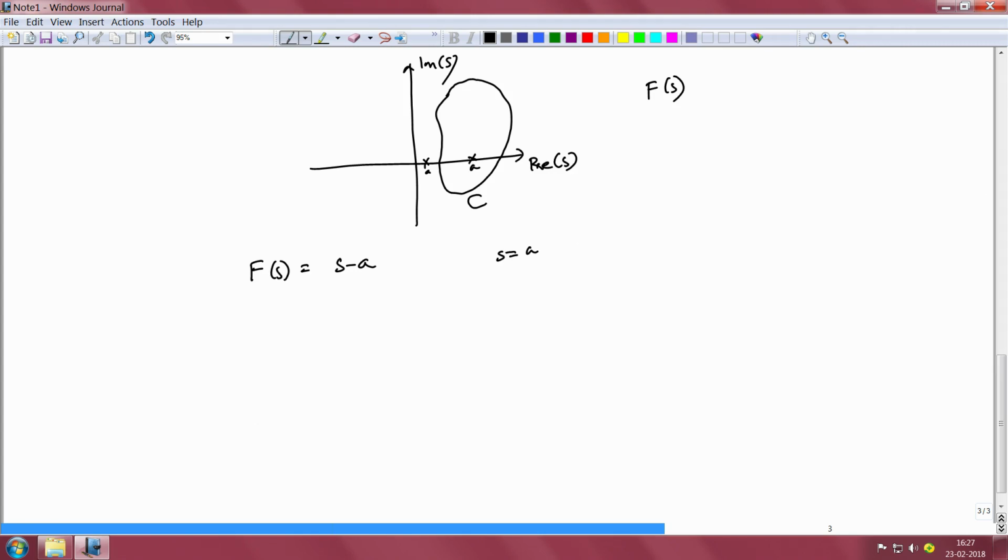suppose we were to impose this further restriction that you are not allowed to locate a within the complex plane, but yet you are asked to tell whether a is within C or not. How would we do it? So, this is where we would have to employ Nyquist, the concepts of Nyquist stability theory.